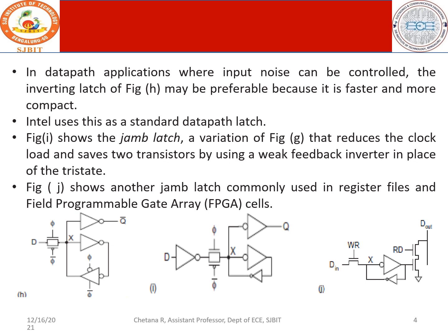In data path applications, the primary concern is that the input noise should be controlled, and the inverting latch of figure H is preferable. Intel uses this as a standard data path latch. This is very commonly used in the company Intel.